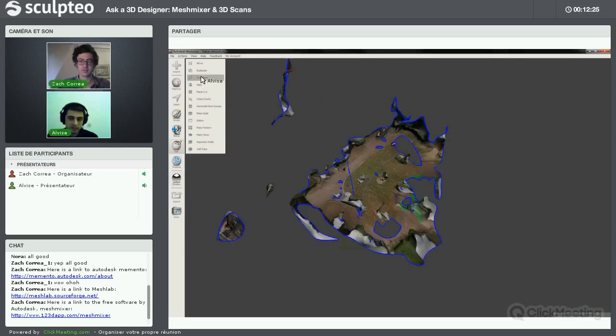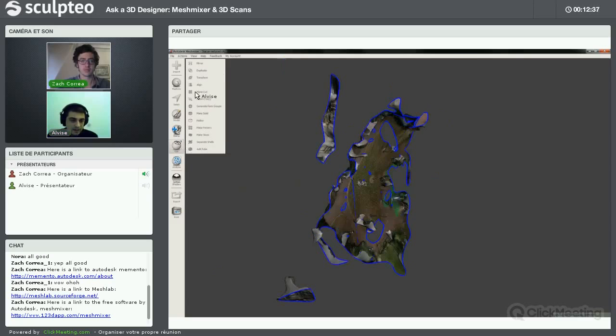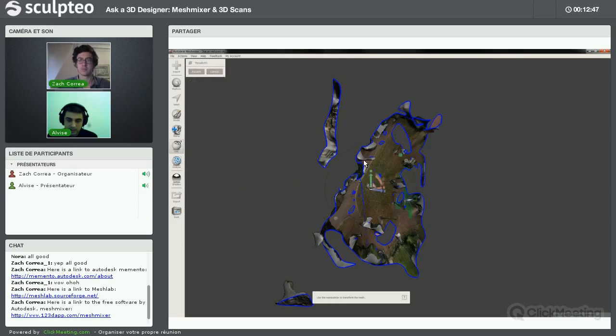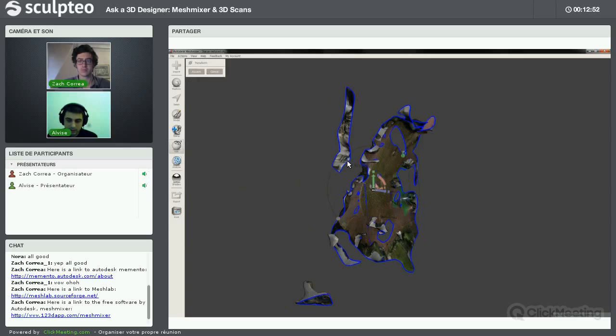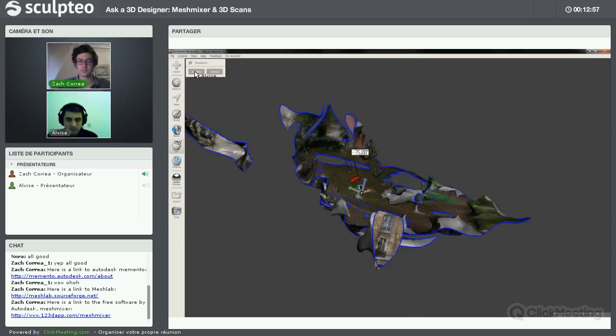First thing I'm going to transform. As you see, the mesh is wrongly oriented, it's rotating in a weird way. This will affect all my work later. So let's go to the Edit tab and click on Transform. These arrows will appear in the middle of the mesh, allowing me to rotate it 90 degrees. I'm snapping each 5 degrees, just going a bit further with the arrow from the center. 90 degrees is perfect. Accept on the top left of the screen.